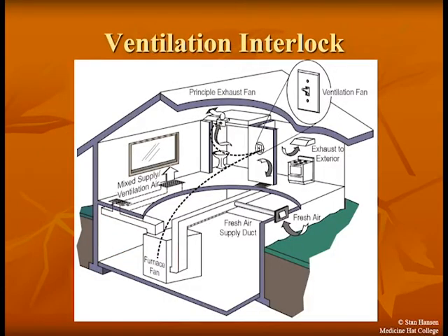As houses are being designed better, they're being built more and more airtight, which means less air leakage for fresh air replacement. This can lead to a condition that's called building sickness. The Alberta Building Code requires mechanical ventilation for any houses; we need to have a way to exchange the fresh air for the stale air. Generally, this system consists of an exhaust air fan and a makeup air system to work together.